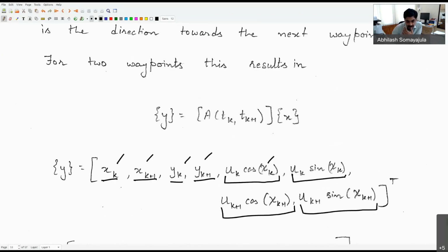Now, the speed at each of those waypoints is usually provided as an input, which we can take. Now the idea is we want to specify how much time it should take to go from one waypoint to the next, and how the smooth trajectory is formulated as a function of time. So we set up this matrix equation y is equal to, which consists of this vector which is known to us. So notice that y is known.